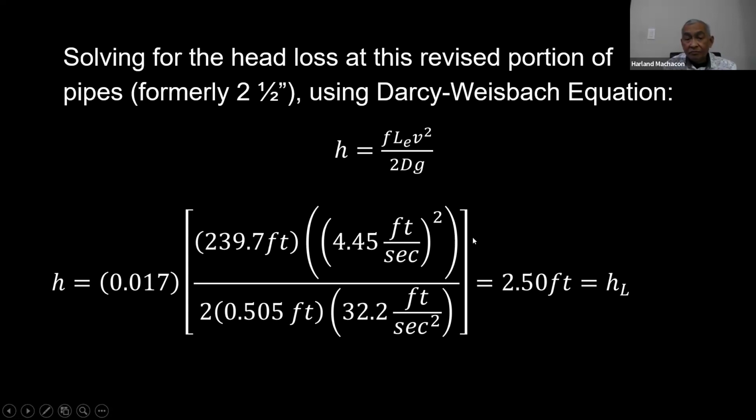My comment, take note that the head loss is proportional to the square of the velocity. So as you increase the pipe size by a small amount, what will happen is you have substantial improvement in your head because it is the square. So the velocity here plays a lot in improving your head loss.